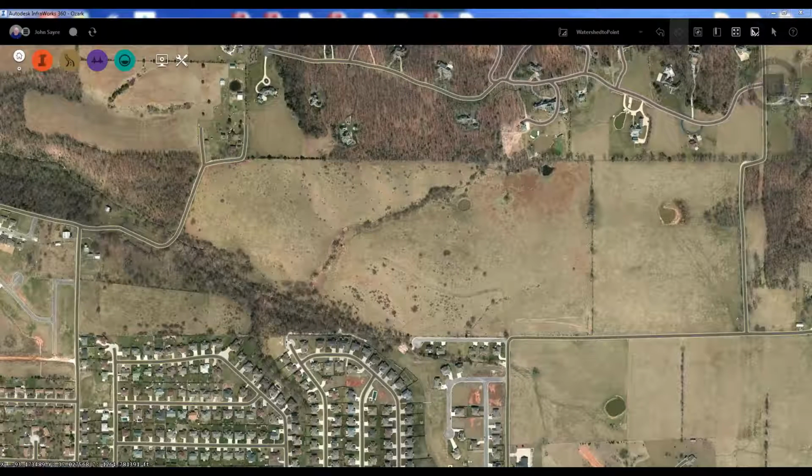To start off by giving you a bit of background about this project, we've been asked to gather watershed information on a new through road that's been laid out. But first, I'd like to be able to show how much contributory area is going to a specific point in our project. So we know that our new road will start at this road here on the east, and we're going to come through the property and tie back into a road here on the west. So we're going to have a couple of stream crossings. So I'm going to select a point, and I'm going to get a total contributory area to this point right here because this is my point of interest.